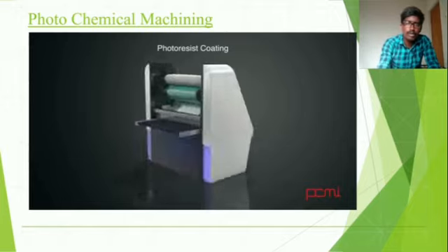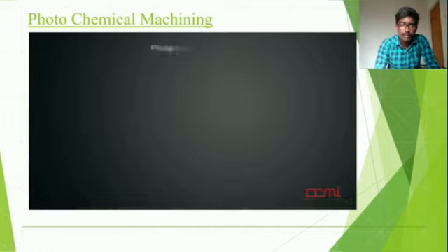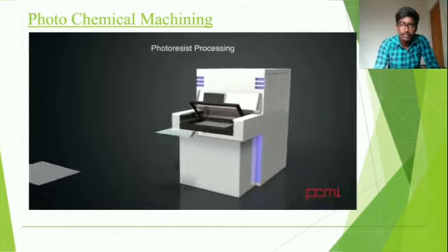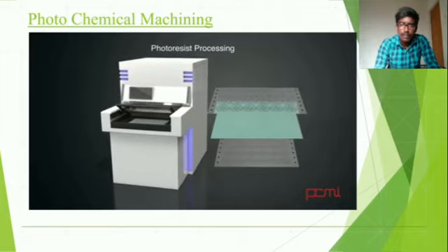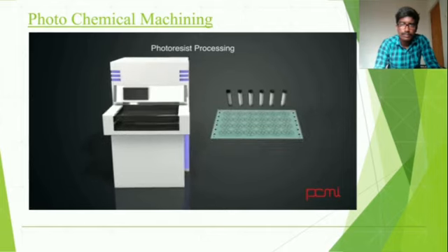The coated resist is sensitive to UV light and resistant to acid. After the resist is applied, the material is then placed between the two pieces of artwork that have been created. The resist-covered sheet is then exposed to UV light to create the desired image on the coated metal.